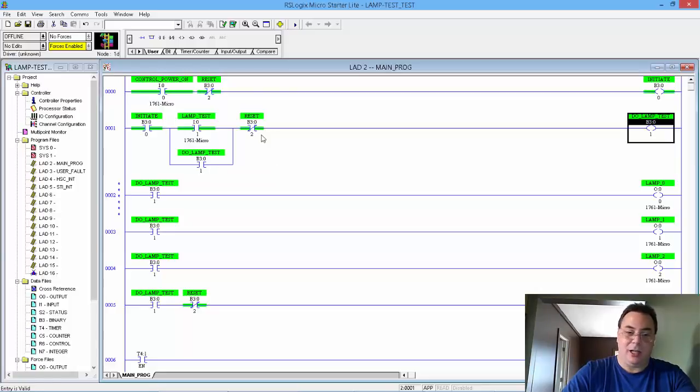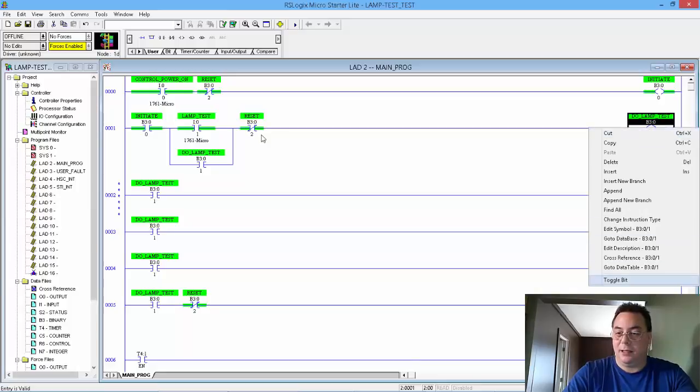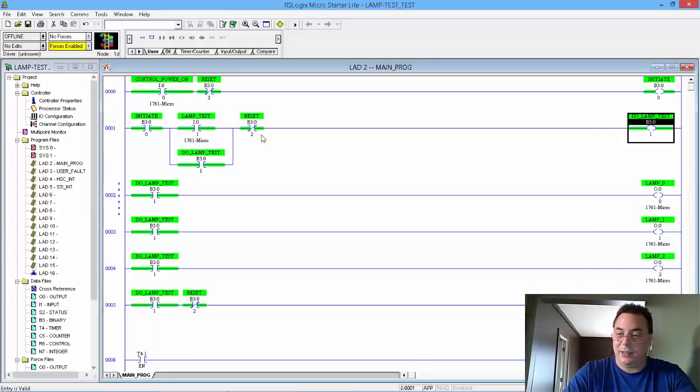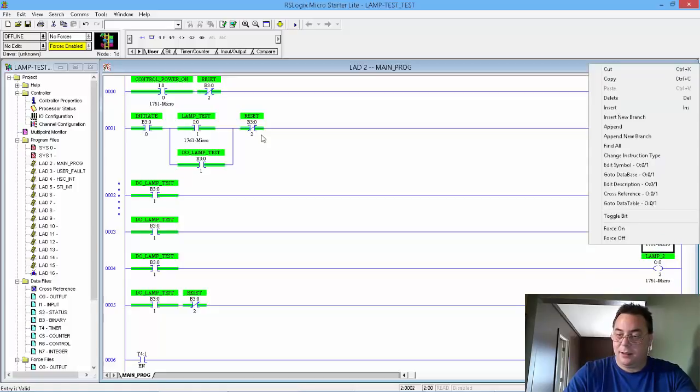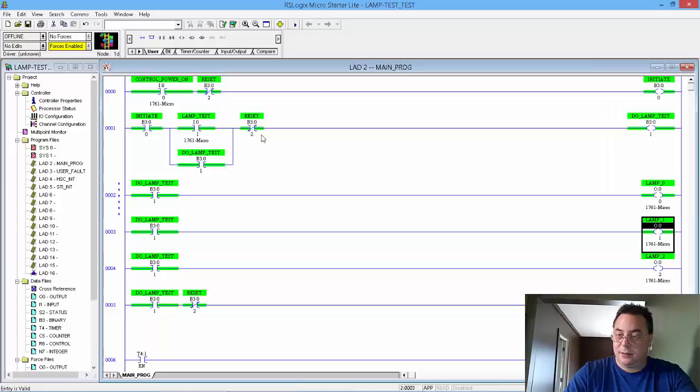It's going to latch, and it's going to start this timer, and it's going to keep those lamps on for 7 seconds before the reset occurs, which you can see I have close contact for reset here, and a reset on the actual timer circuit itself. Okay, so we're going to go ahead and toggle that on, and now you can see all our 3 lamps would be on.